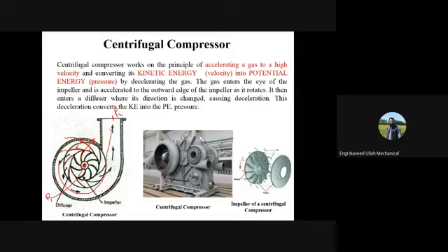If you remember, we discussed. Now, what is the energy transfer over here? The energy transfer is that the fluid is entering the impeller at low energy, right? And the impeller rotates. And who is rotating this impeller? Obviously, the input. This is mounted on the input shaft. The work is consumed, or the power is consumed by this impeller, and that kinetic energy is converted to pressure energy, as we discussed. So acceleration and deceleration takes place, and that's why the pressure is increased.